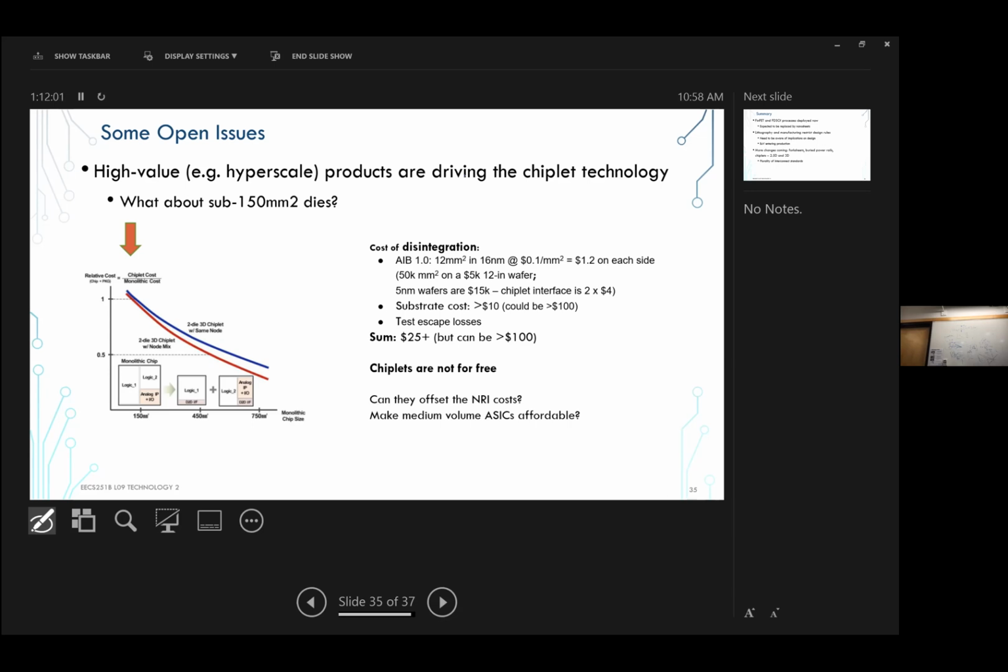So each of these interfaces costs of the order of a dollar or so. So that's a big cost. It is unlikely that we are going to see chiplet solutions or chiplet breakdown into some products that are less than $50. So there are plenty of products that are in between an iPhone and a desktop that are being made in relatively low volume, where NRE is really, really expensive and is pushing them out of that market. People are trying to avoid these solutions.